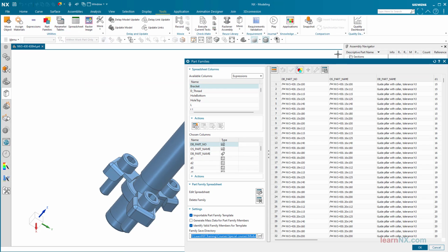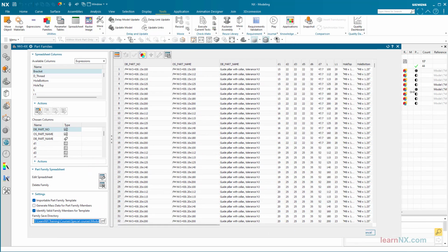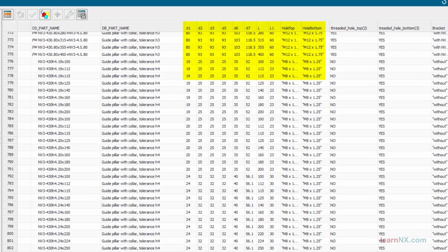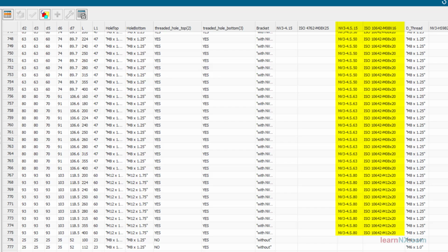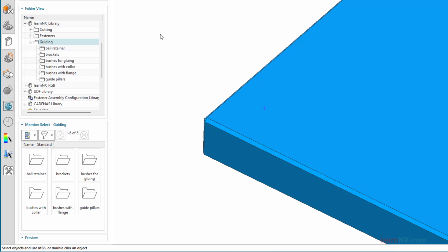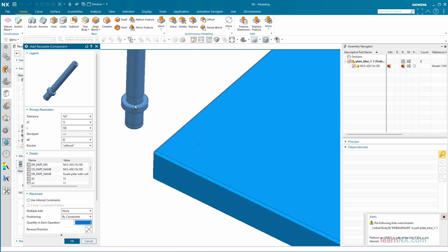With this command, the parameters of a master part can be linked to a spreadsheet. Each line of the spreadsheet creates a part or an assembly. Parameters can be changed here. Work steps can be switched on and off. And also components can be replaced. This allows you to quickly create your standard parts and assemblies, which can be conveniently made available to your colleagues in a library, which are then installed in a predefined manner.